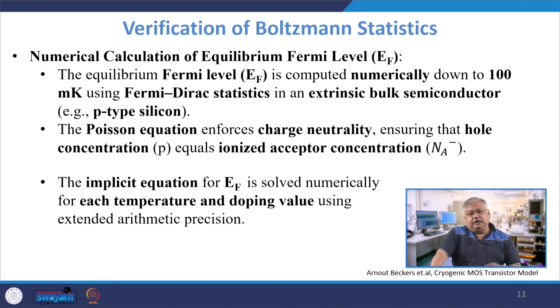So, the idea is to try to find the value of EF, which is the Fermi level, at various points, and these are numerically solved and analytically expressed. Plug in the value of temperature and doping concentration, and you start getting a fresh value of EF. And this fresh value of EF will be helpful for you to actually design the variation of the charge carriers, as you do when you actually match two elements.